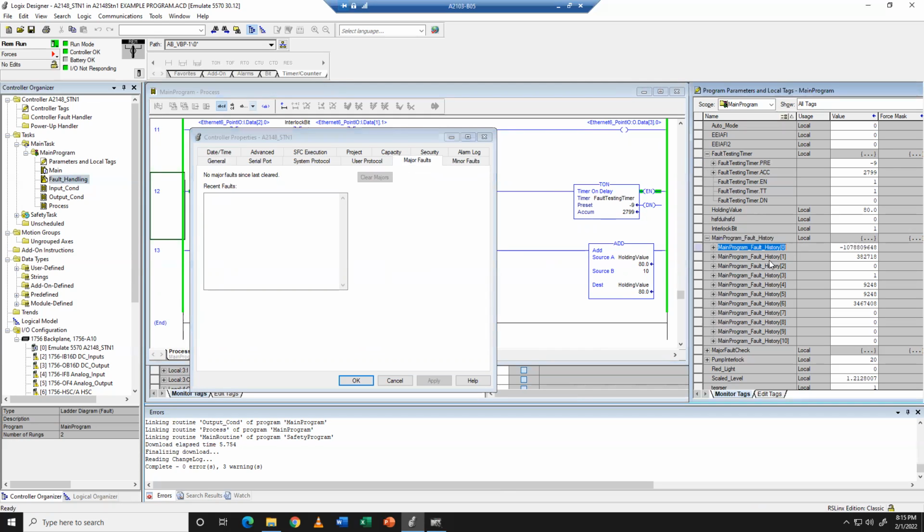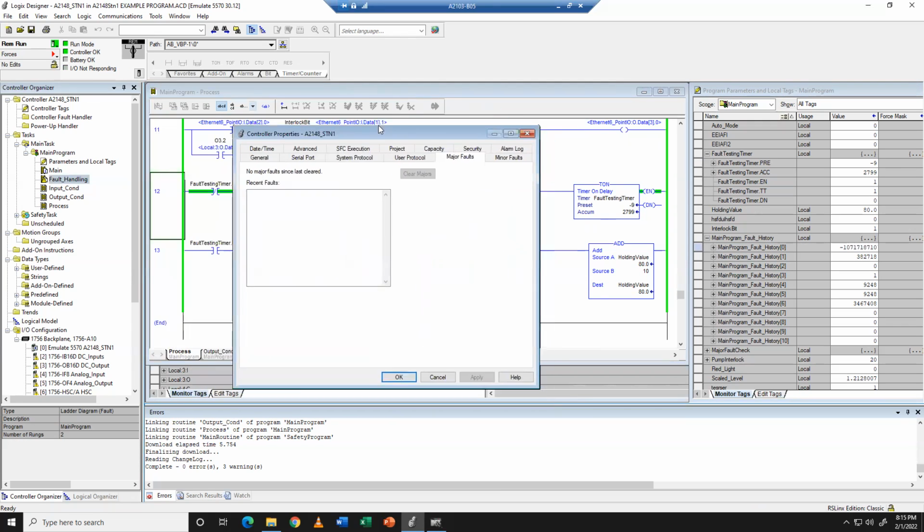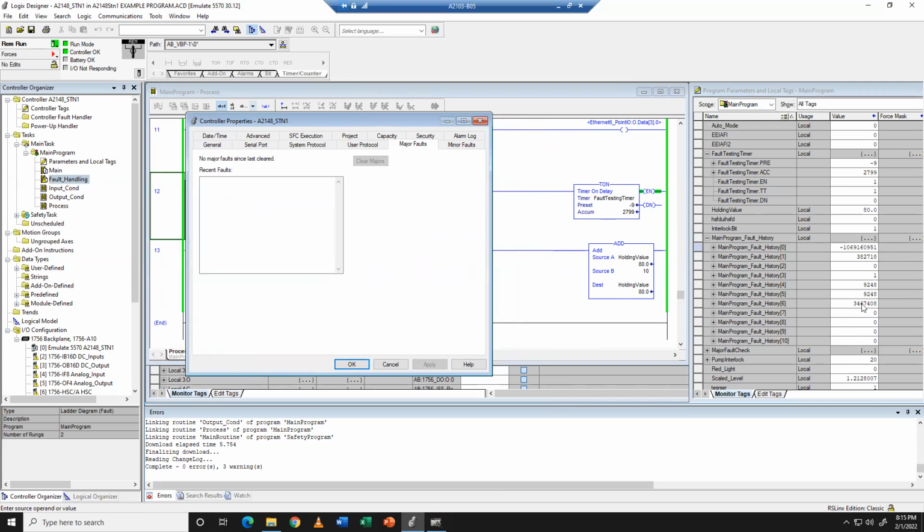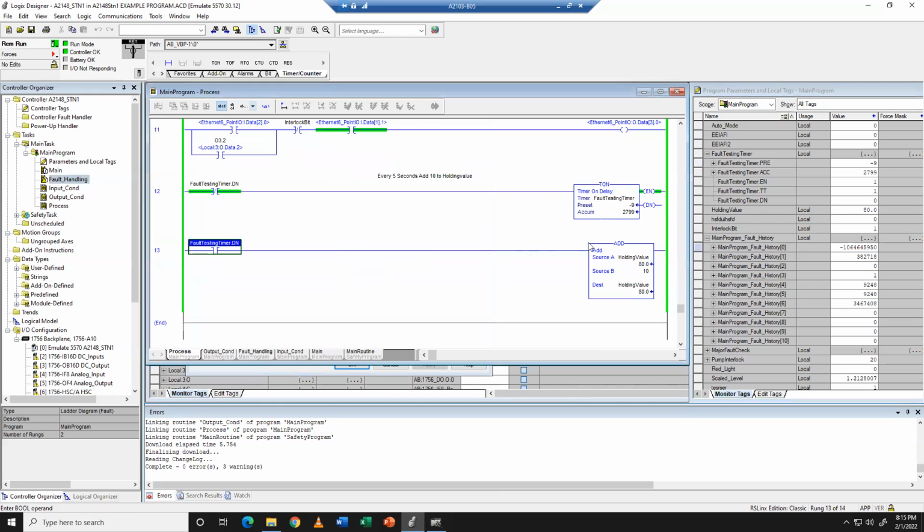this is the one thing that's kind of one of the reasons why I don't love clearing faults. There's a problem with your code. Something's not working properly. This subroutine is faulted. And because the controller is still running, you're just automatically spamming the reset button. This is like holding the escape button forever on a machine to prevent it from locking up.